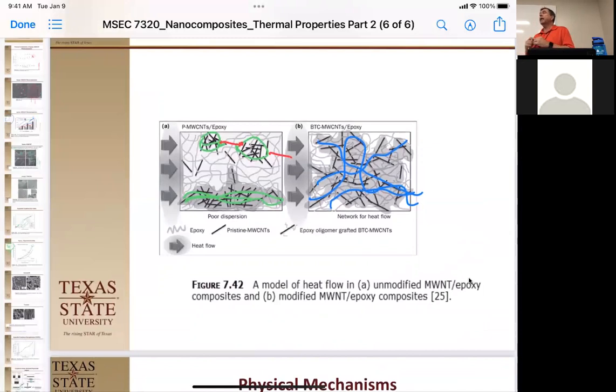The polyester actually has a lower inherent thermal conductivity. So I think, well, it depends also, because in the epoxy, you only have a set it and forget it kind of thing. In the polyester, you can reprocess it, disperse it again, stretch orient it. You can do a bunch of different things after the fact. The epoxies, because they're thermosets, however it was when it cured, that's what you get. So yes, you probably can get enhanced properties, not just by the polyester itself, but by the fact that you can process it afterwards.